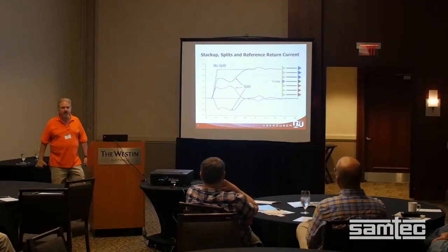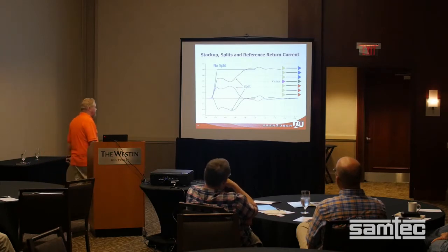That's what you give the engineers, and you put that in your stack up, saying data has to be on this layer. Do I care if it's on that layer? No, I care because that's where the reference is that you need to be on. Most of you already do that, yeah? I still see some guys that haven't done DDR before and they switch them all up and it never works. You need to keep track of that.